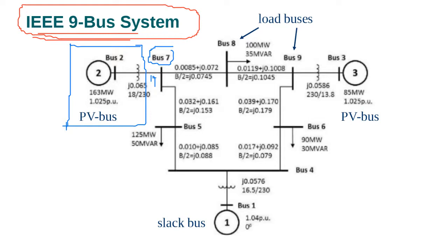Maybe as we increase the voltage, the current will decrease. Very good. So for the lower voltage, 6.6 kV, we need very high current, because the power will be the same. The power which leaves Ras Bufantas also goes to Saeed. That's why we need a much thicker cable, whose diameter will be huge. So we only bring it to the substation, very close, of course.